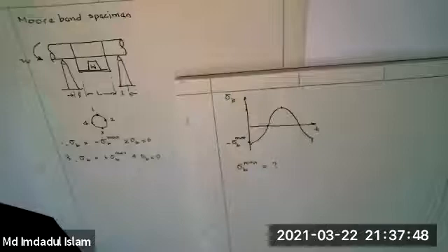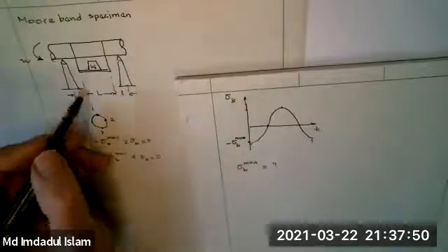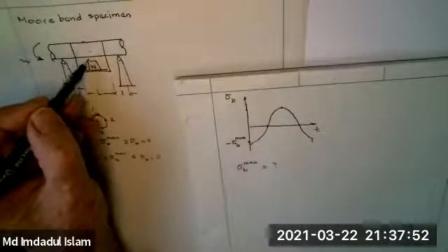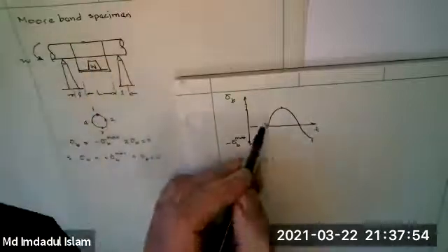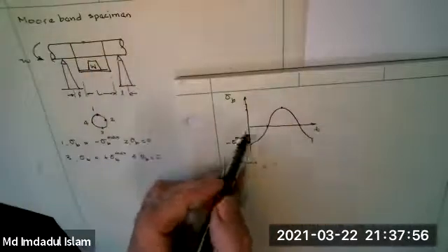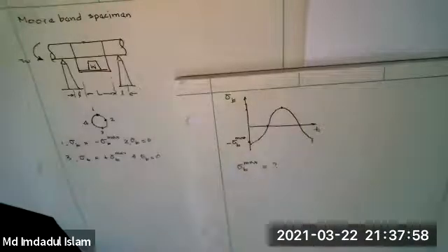Okay. So every time it rotates, this part starts off the top, moves to the side, moves to the bottom, round. In 1 revolution, it sees this oscillation between minus sigma B max and plus sigma B max. And you can have 1,000 revs per minute. And so I've seen lots of these cycles. In order to understand this test, we need to get what sigma B max is.